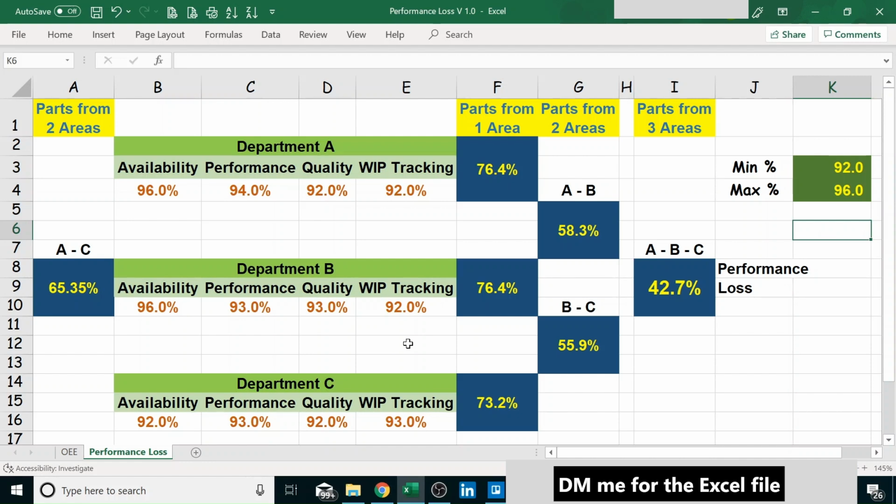Can we substitute 4, 5, 7, 12 machines, very manual or close to manual, semi automatic, with a very, very automated machine? We're going to save on processing time, we're going to improve our quality, we're probably going to reduce our scrap because those new machines have technology built in, software built in for nesting, which means our scrap is going to go down. Any material, wood, metal, whatever. And we're probably going to save energy, maybe, because they are very efficient also in energy, and also footprint of our manufacturing plant, because we're going to substitute several machines with that one.